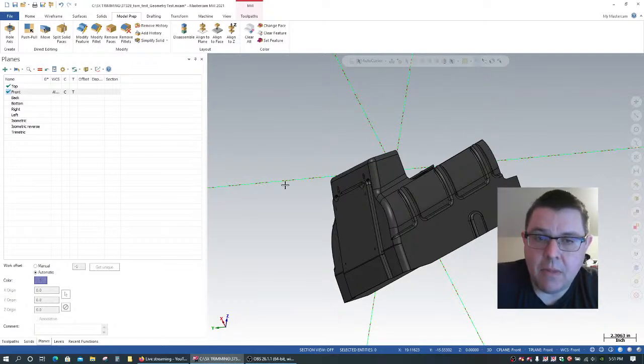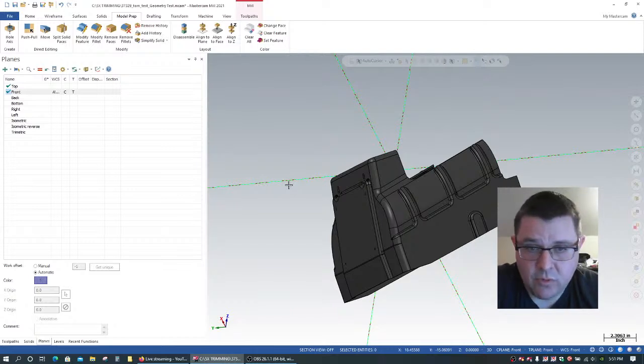People that program aerospace parts typically get the part coming in aerospace coordinates. Now what that means is that for, say, a part from Boeing, you get a piece for the wing. You get some rib or some station or some part that comes in, and it comes in what they call airplane coordinates. And so there are terms in the manufacturing world for manufacturing aircraft, like waterline.